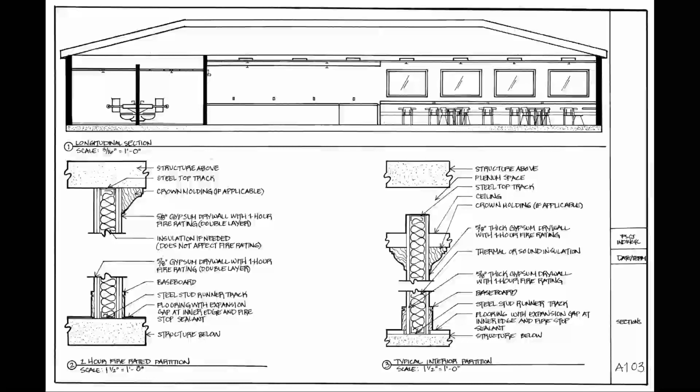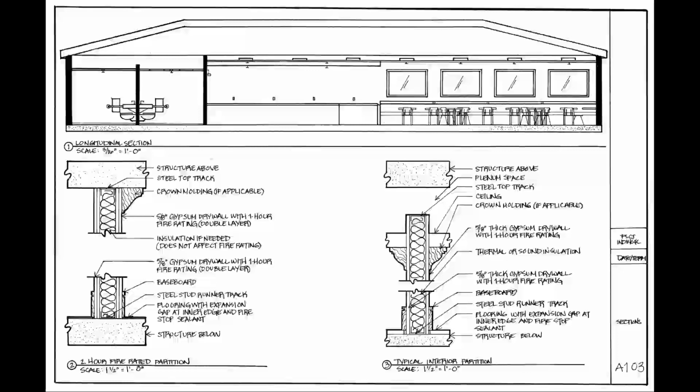The other thing I want to tell you about a section is that it's very similar to what you would see in an interior elevation. In fact, you may create interior elevations, but an interior elevation is simply what a viewer would see standing in one spot and looking in a direction. A section cuts through all the walls and the ceiling and shows what an omnipresent force might see, for lack of a better way of explaining it.